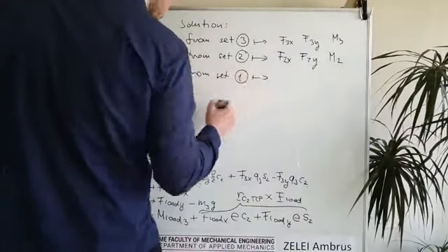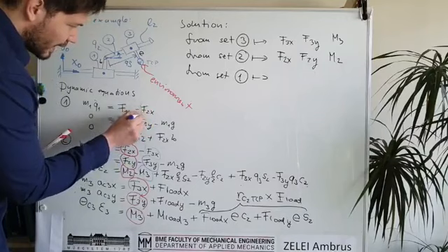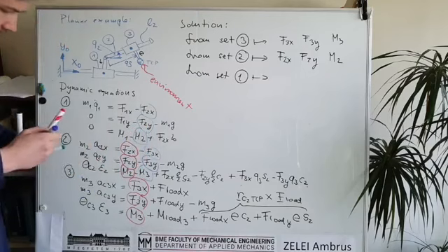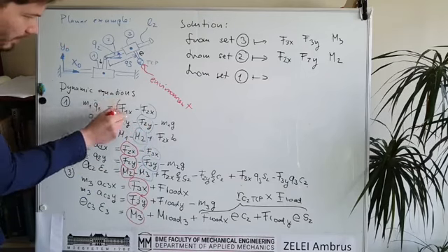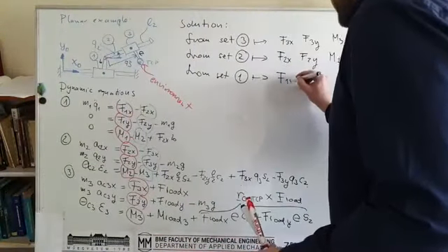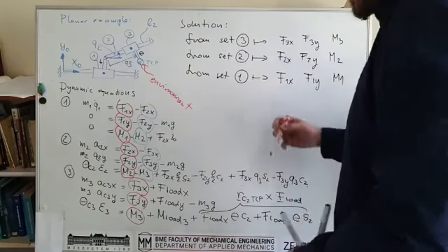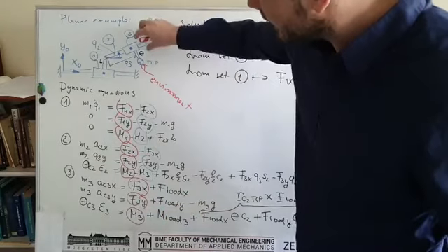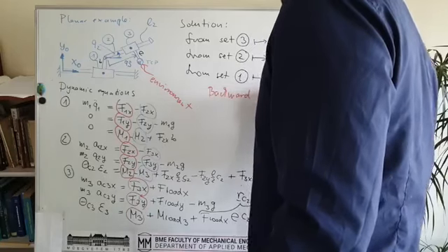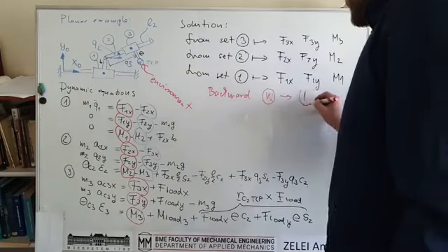And from the first set of equations, from now it's quite trivial. So we already calculated these unknown joint forces and joint torques. And joint torque, there is just a single torque. And we can calculate our unknown joint force parameters. And this is why we call it backward, because we start with the last link and go backward to the first. Okay, so this is backward because, in general, we go from n to 1.